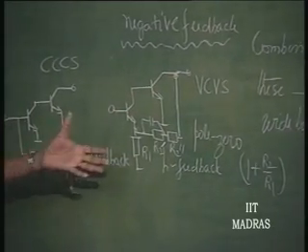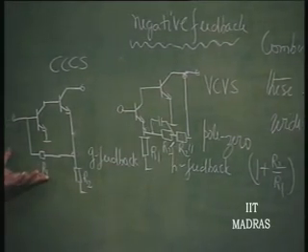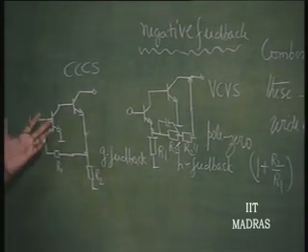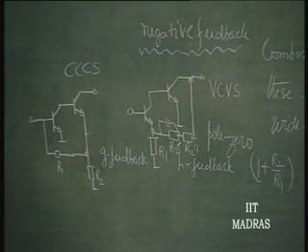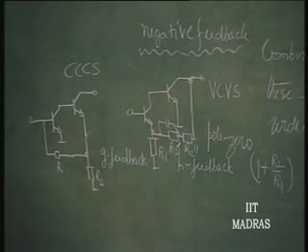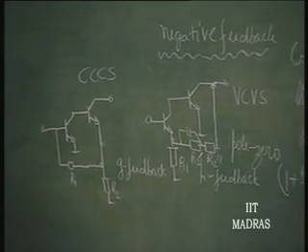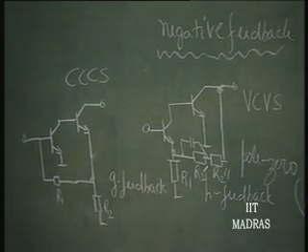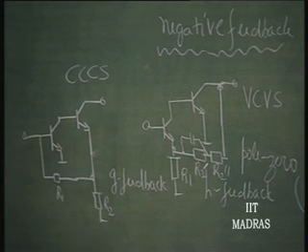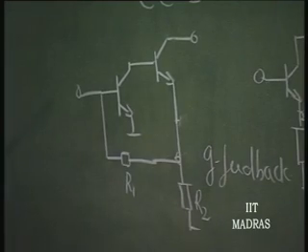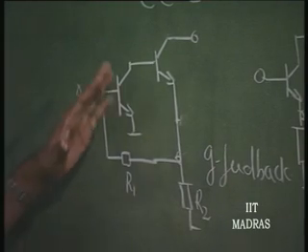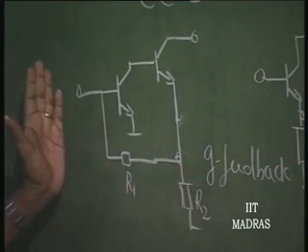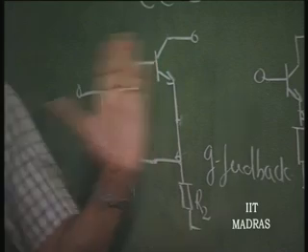Beyond these 2 stages, normally that means connecting 3 amplifier stages, it is very difficult to make it work suitably as a wideband negative feedback structure, because invariably the oscillations persist. It is very difficult, because the number of time constants increase to 4, minimum 4. So, it is enough if we discuss all these amplifiers, which we have already done, as wideband structures.